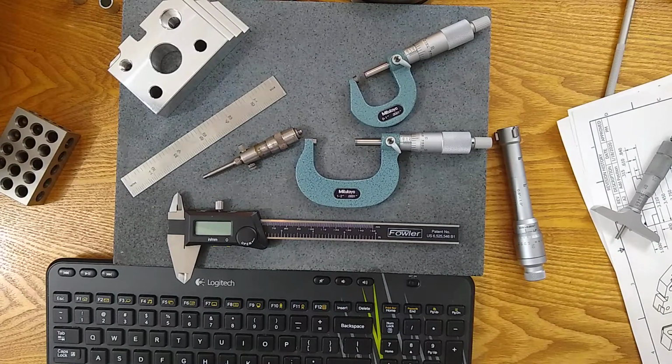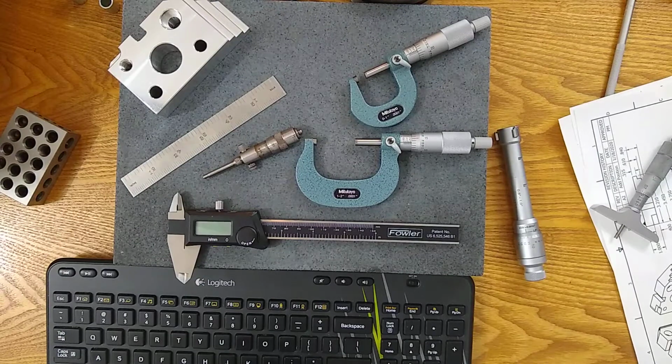And these accuracy numbers, they're highly dependent on length. So they're highly dependent on the hardware. So when you're buying a CMM, if you've never used a CMM or never researched how you purchase them, you buy the CMM, but you get to choose the head that's installed, which is the probe head.